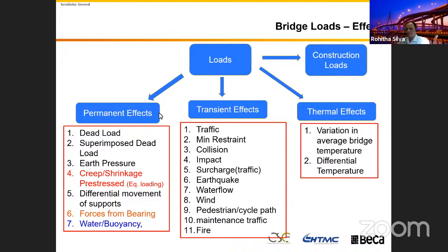So when we talk about the permanent load, it's a dead load. Of course, the self-weight of the structure. Superimposed dead load is a form of dead load, but we use it separately. You will see in the next slide. The earth pressure we inherently have, because behind the bridge abutment we have a backfill. So throughout the design life, you have earth pressure.